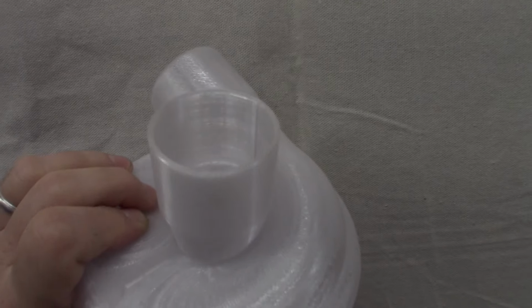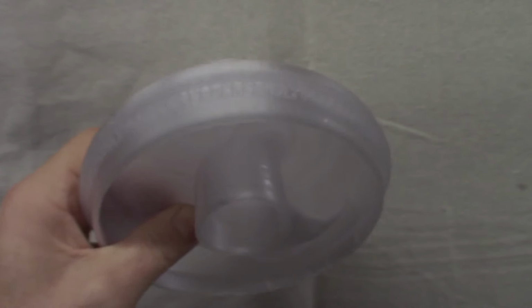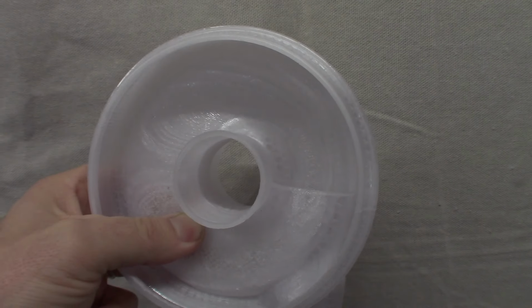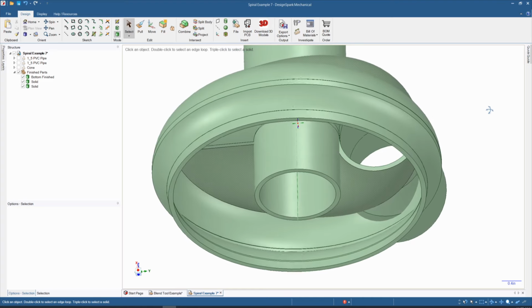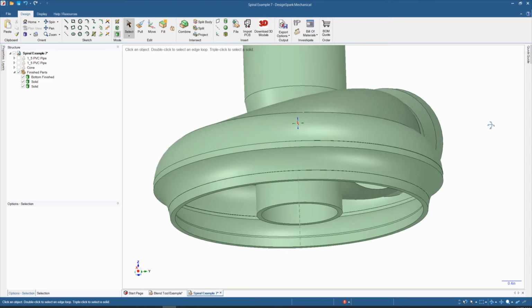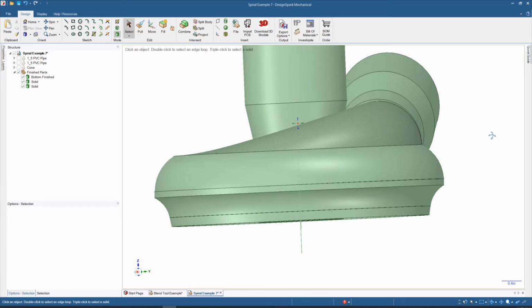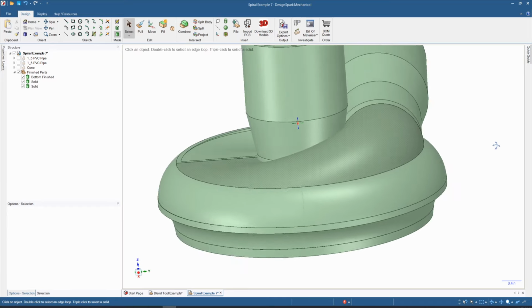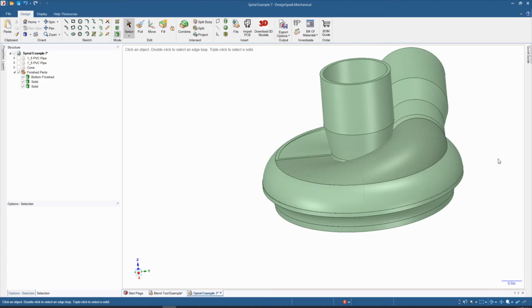If you are making 3D printed parts and you are free to make any shape imaginable, then the Blend tool can be your new very best friend. The first thing is this tool allows Designspark to generate the surfaces, so the results are not completely controllable or predictable. Sometimes you have to try several approaches by trial and error, but remember, you can always undo it and try it again. But in the end, the Blend tool allows you to make some amazing shapes.